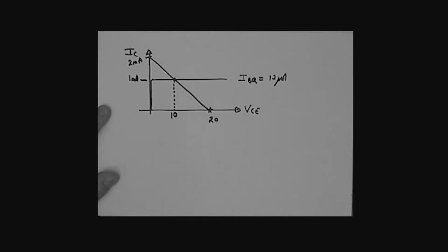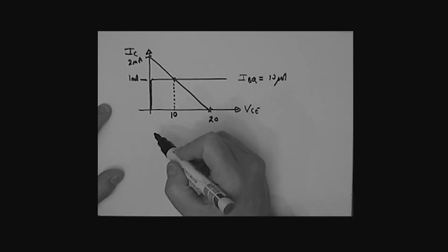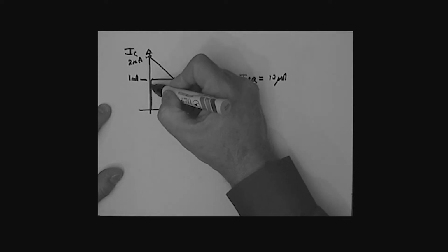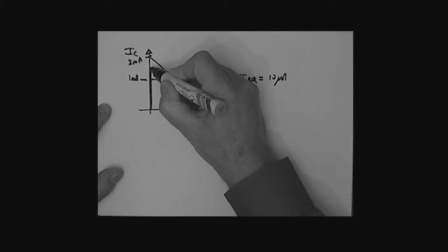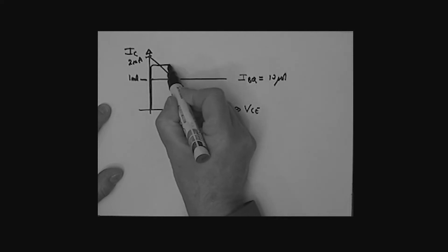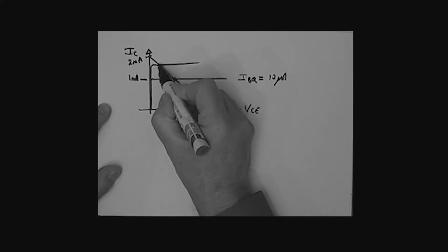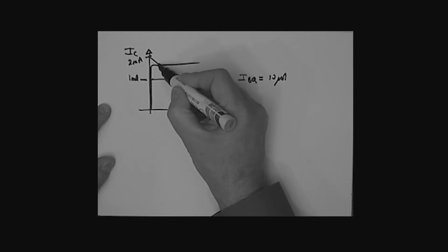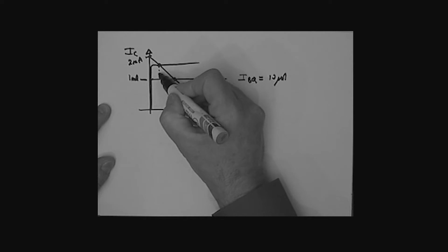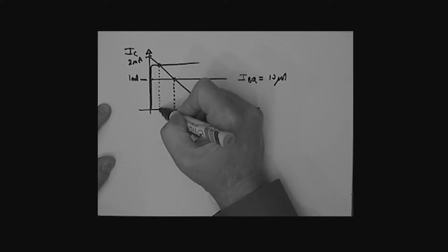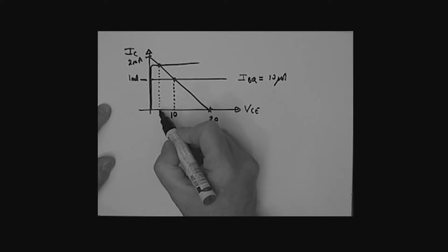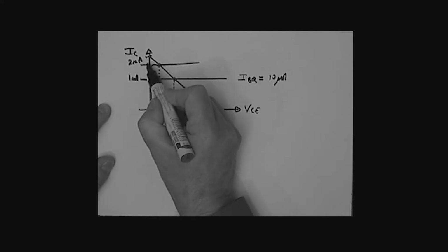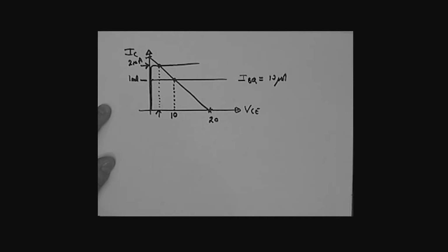So what we have is, due to that larger base current, due to the presence of that signal, it's as if we've moved to another characteristic curve, let us say like this one here, and so we effectively have moved our operating point to, as it were, a new value at that instant in time when the signal source had reached half a volt. And so we now have a new value of VCE and, if you like, a new value of collector current.